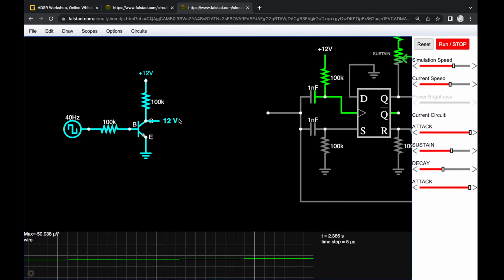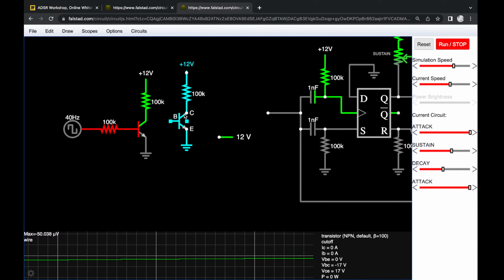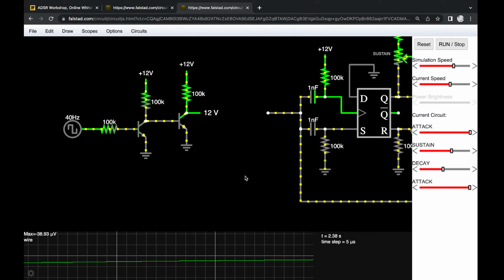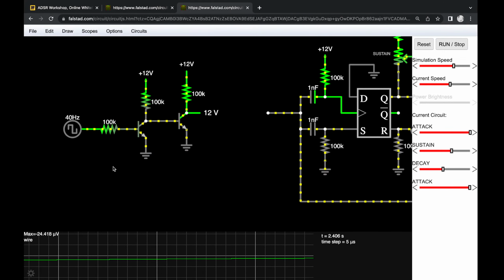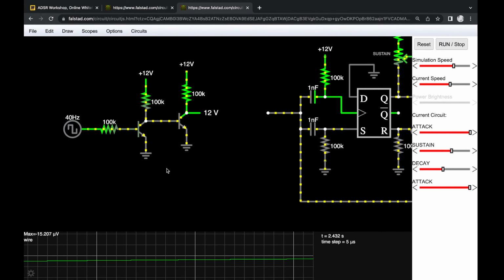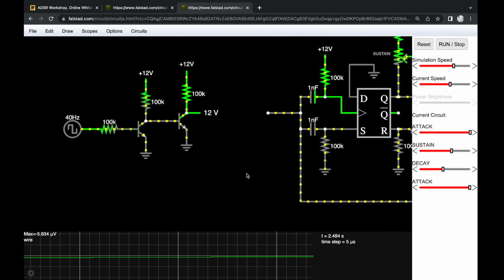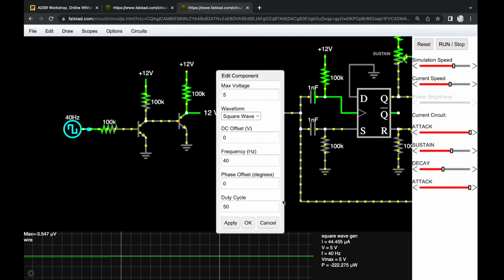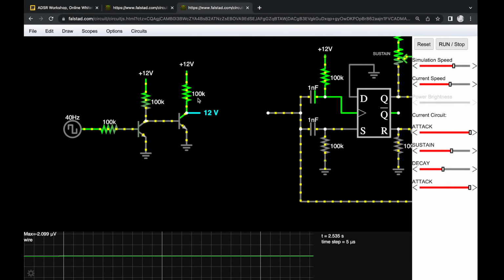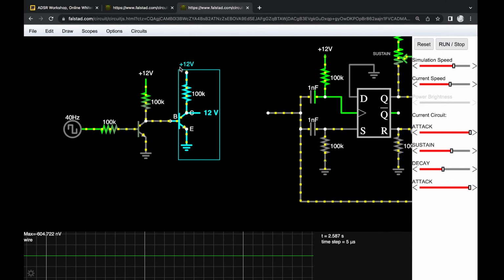So it's safe to assume that we can simply take another one of these and set it up over here. And if we now apply the voltage from here to this transistor's base, then we should get the desired functionality, right? You can see that here. So clock goes high, this goes high. Clock goes low, this goes low. That's great. Also, this is just 5 volts, but the output here is actually 12 volts. So this kind of works like a comparator, if you will. Not really, but kind of.